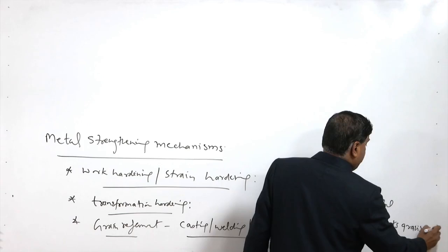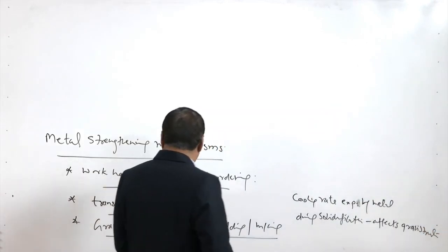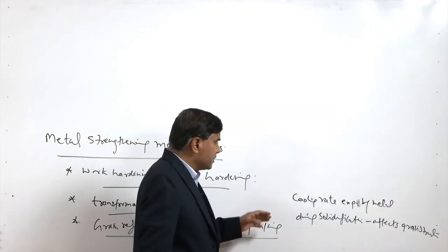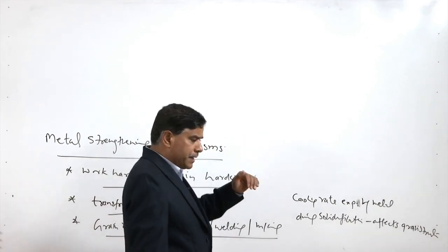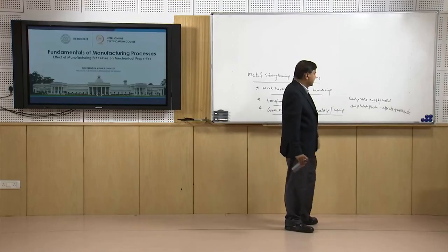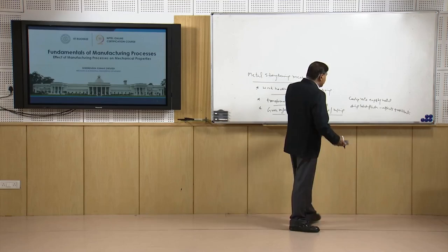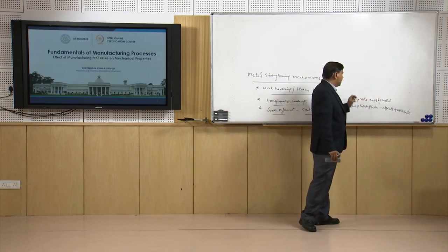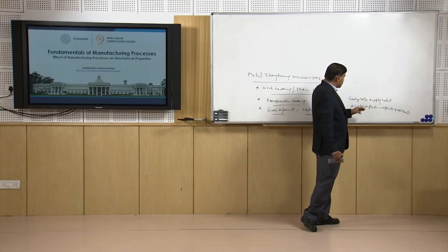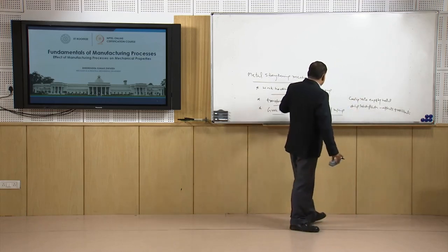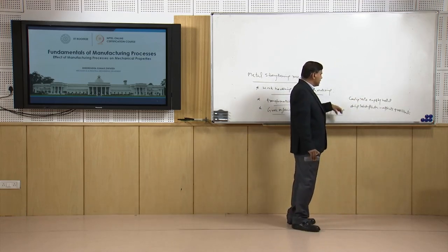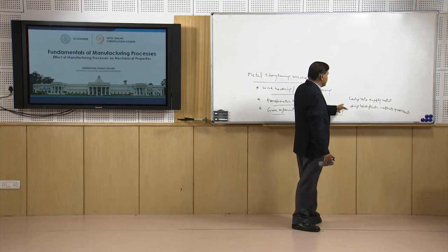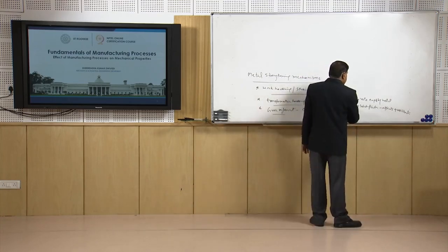So, in general, you know, the finer the grain structure, the better the mechanical properties in terms of strength, hardness, toughness and ductility, and it is the cooling rate experienced by the metal being processed either during the welding, casting or thermal based processes of machining, the solidification.